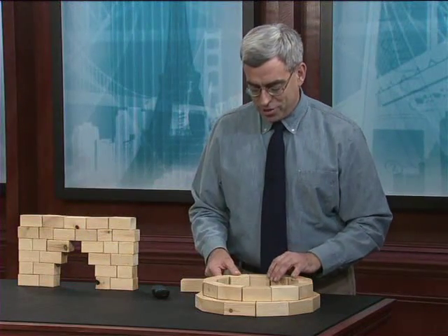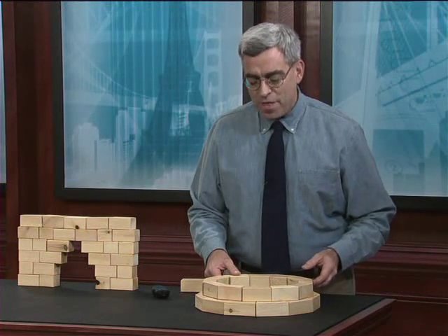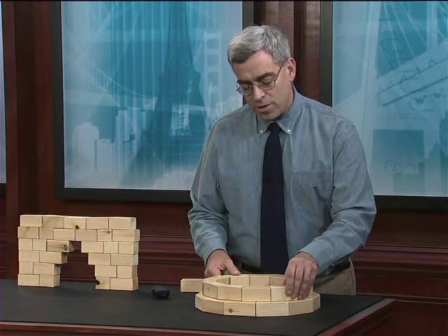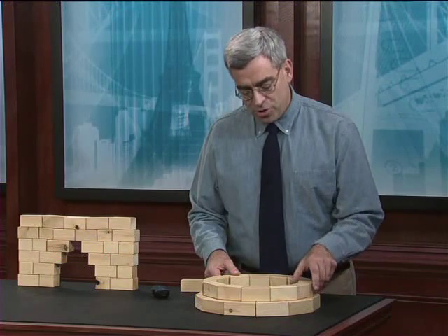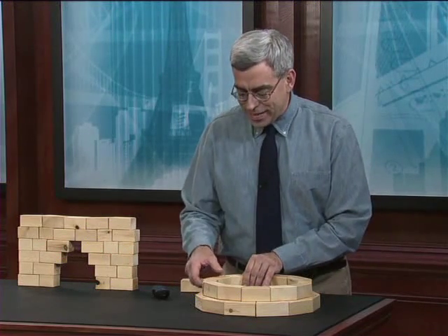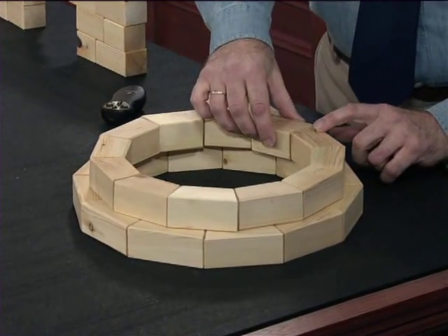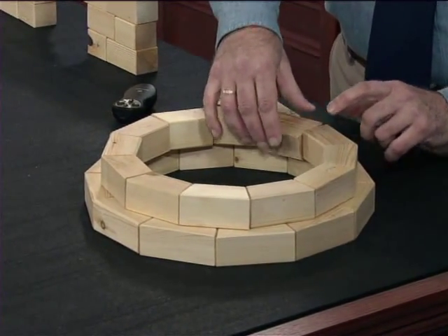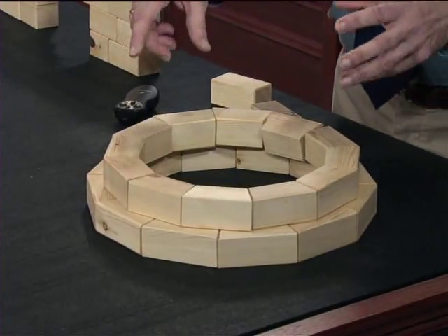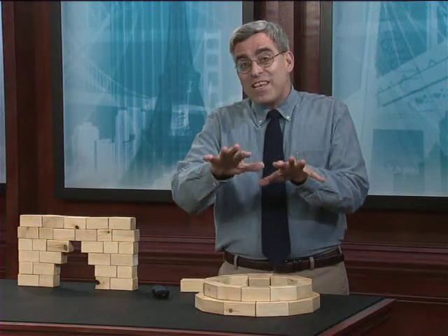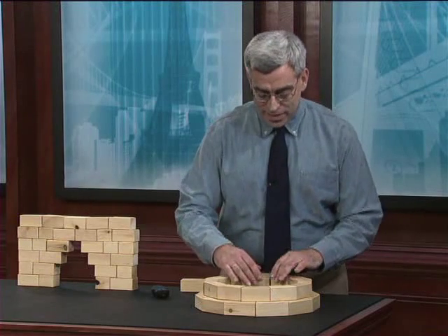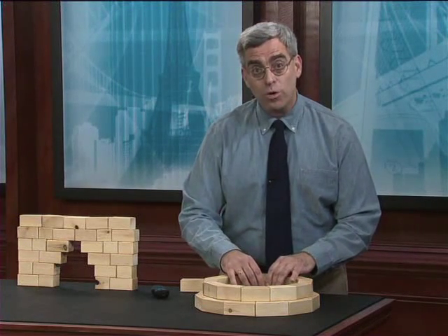And you'll notice as I try to position the stones that there is a problem with this configuration. As we put the stones in position, notice that they have a tendency to tip inward. That tendency is occurring now when I only have one additional layer of stone. And as I build successive courses of stone, the tendency of the individual stones to tip inward is going to get even greater.